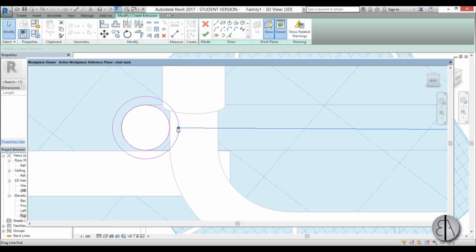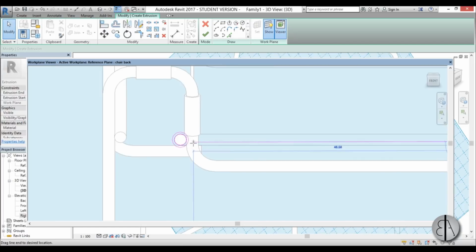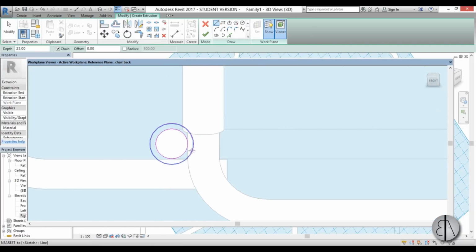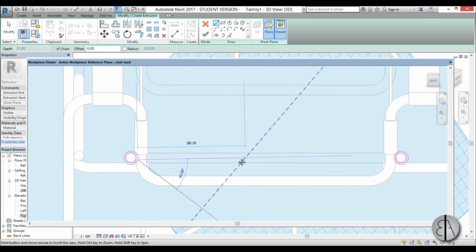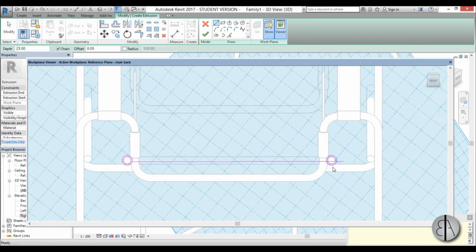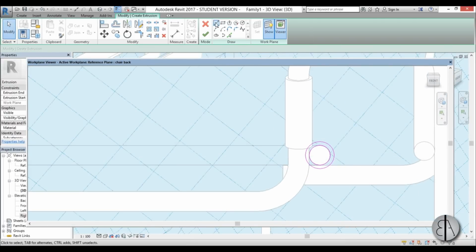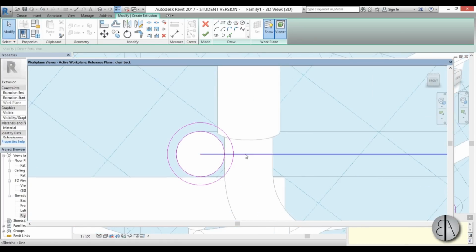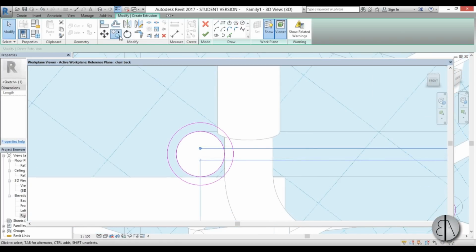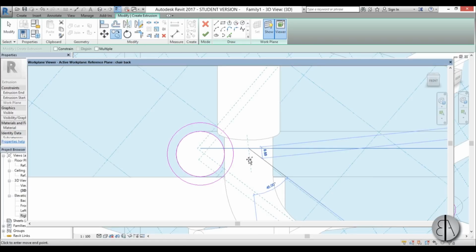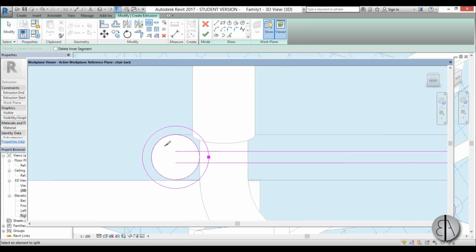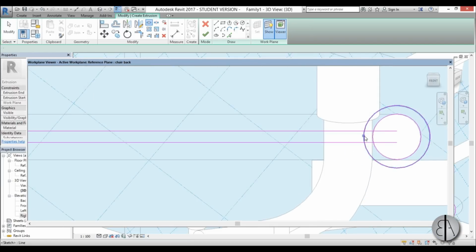Okay, you can see that isn't really right. Yeah, it's a bit crooked. Let's just create this one over here. If you can't really center it, try going from a circle center to other circle center and then pull it up a bit and then just copy it down. Like so. And then we go to split element, split here, and just use trim and extend.